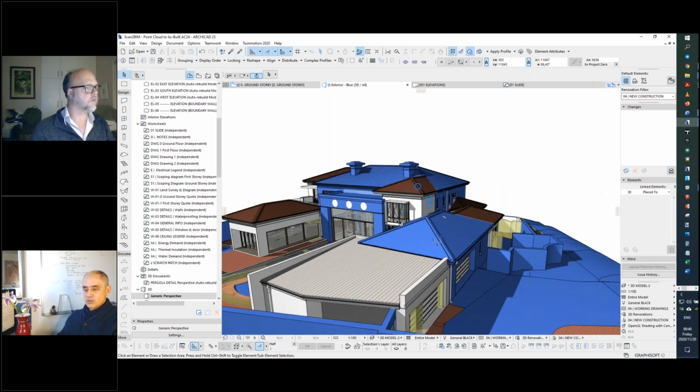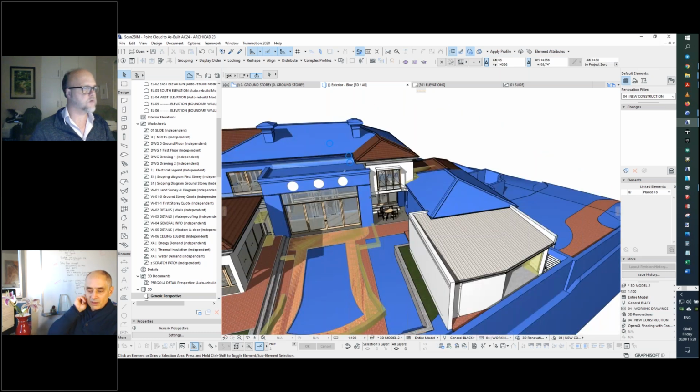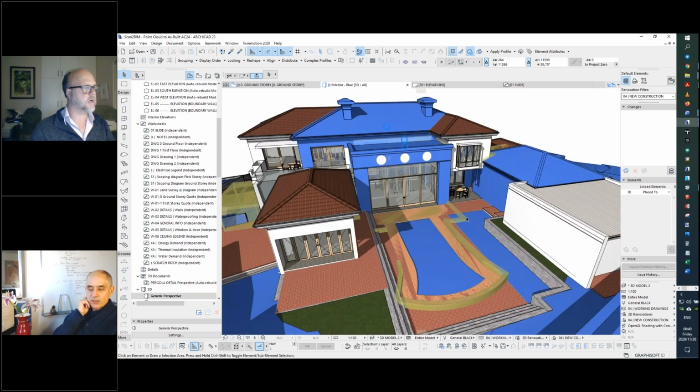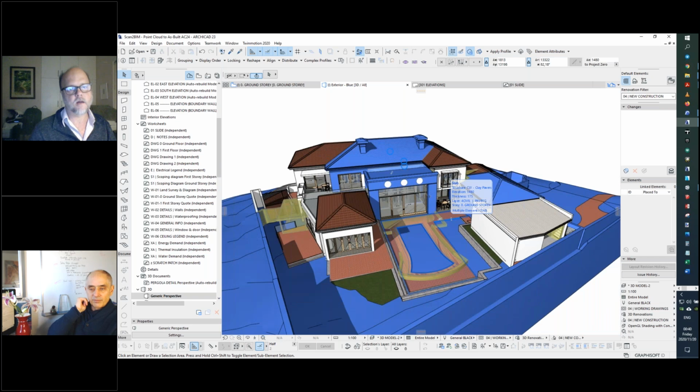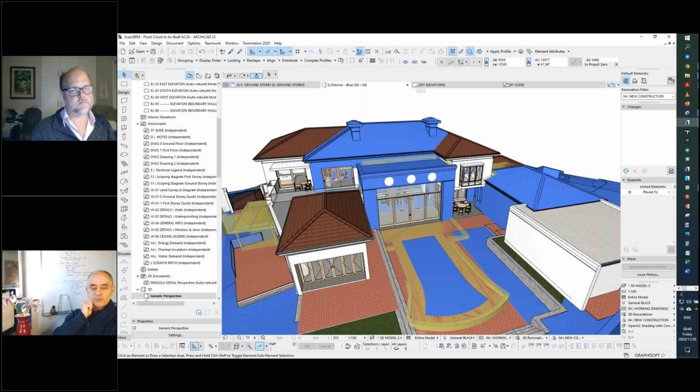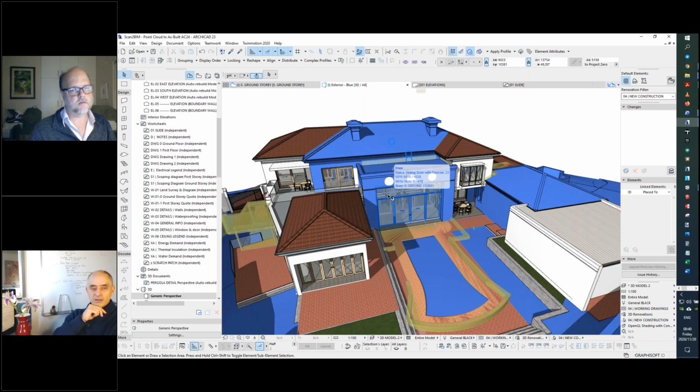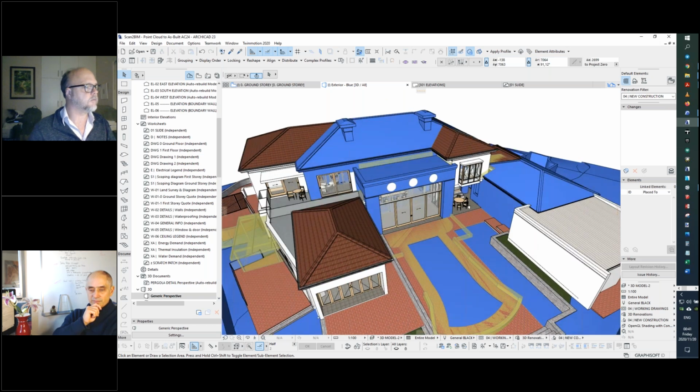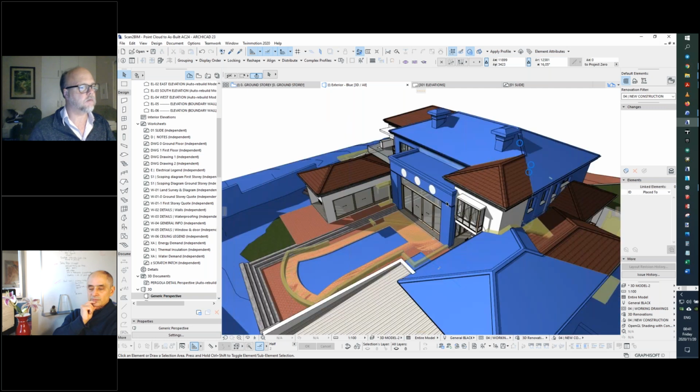Okay, excellent. By the way, there's a question from Rob Warren saying, how many stations were required to scan the property? Stations, scan points. This was about 220 scan points. All right, so 220 places where the device was put down and rotated around to get data? That is correct. And obviously this was only the interior done, and not even the full interior. So if we just have a look at the scan again.